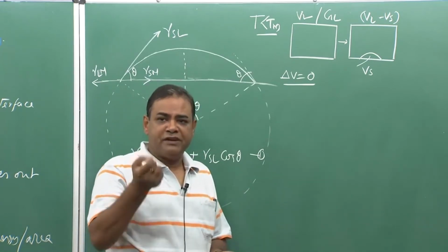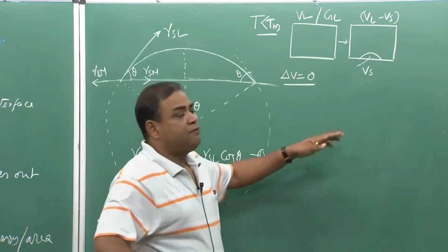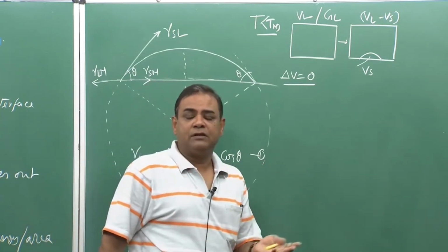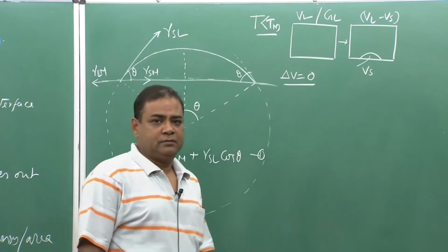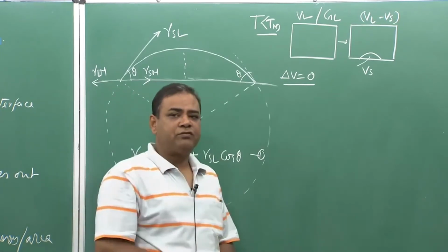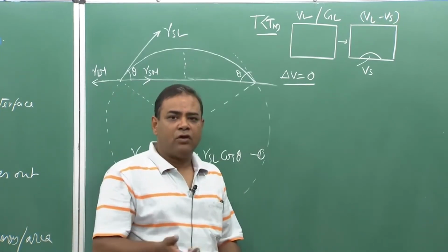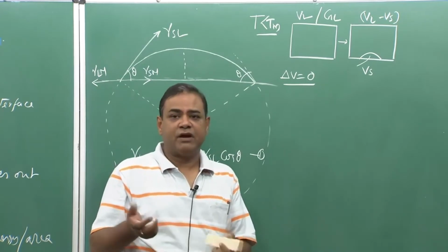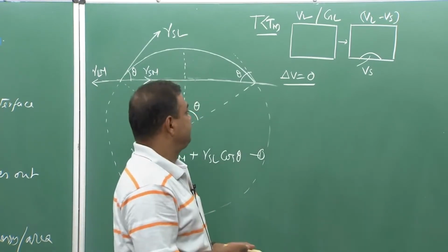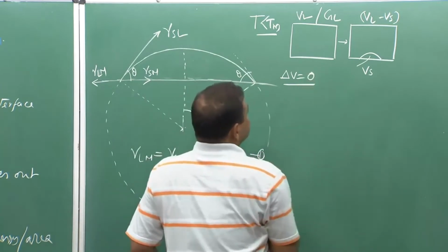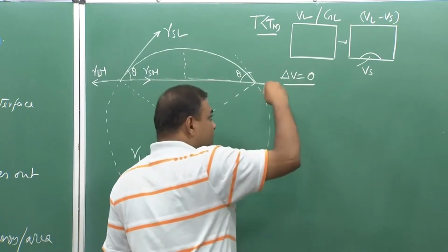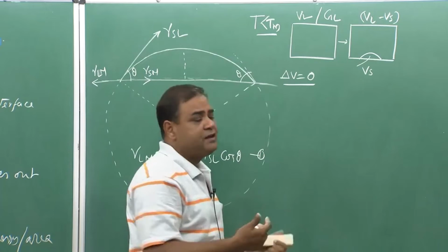But in case of liquid metal, for example aluminum or iron, when the solid forms, the volume decreases. That is what gives you the sinkage problem in casting. We are taking this assumption to have a very easy treatment of this problem.